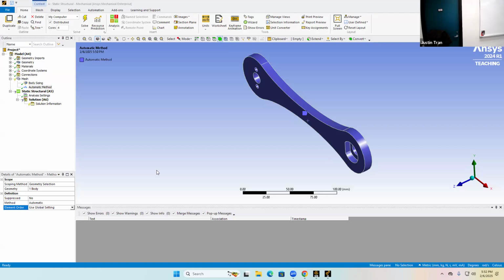That was pretty good. Yeah, you're able to get a hex mesh, which is good. One thing, actually, go back, click on mesh. One thing I actually look for a lot is, if you're looking at the part in this direction, you see that there's kind of 2 layers of elements. That's actually pretty good. That's one thing that I look at for these kind of meshes. Yeah. Good.